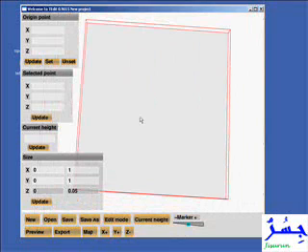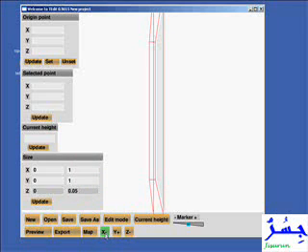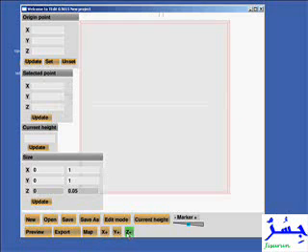Okay, you also have X view. You can place the view along the positive X, negative X direction, or Y, or Z. These are pretty much not useful when you're actually entering the points, but it would be useful once you have enough points to create the 3D surface, and actually be able to preview it and maybe edit it while you're looking at it in 3D, which I will describe later on.